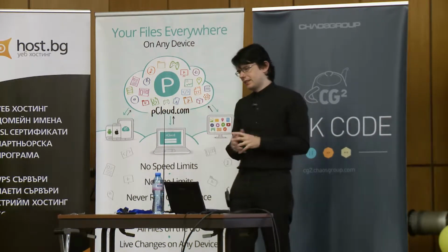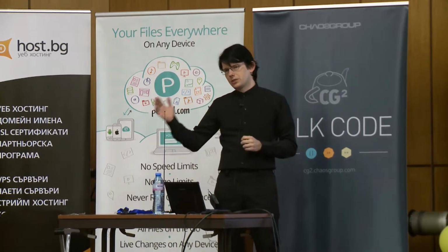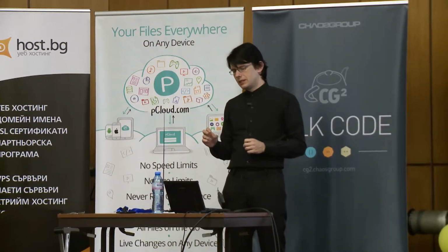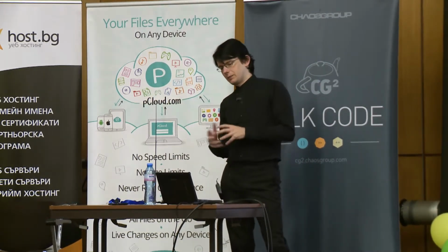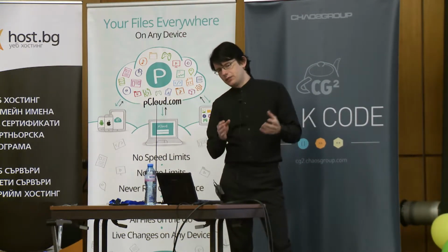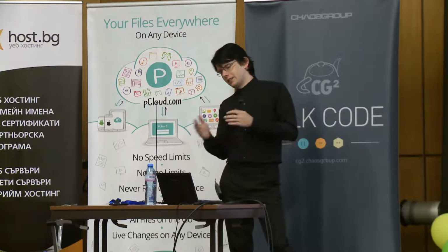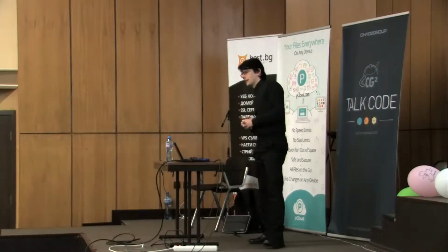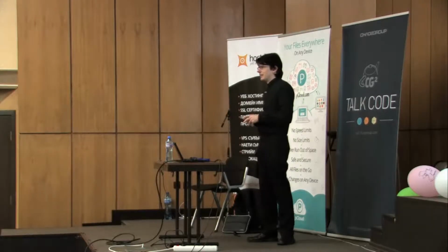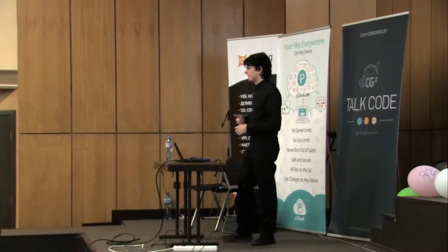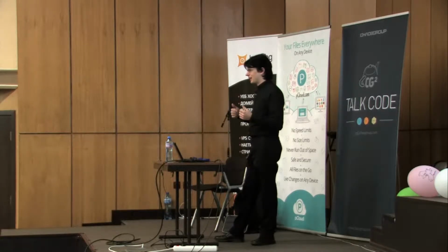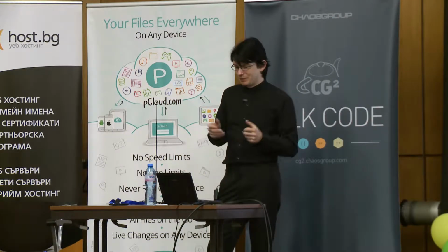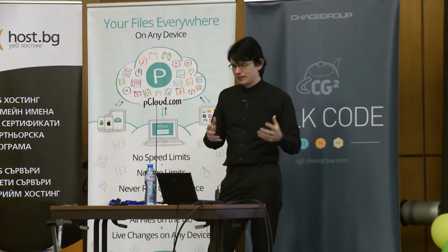The other idea is to convert not to a 0IF, but to a very low intermediate frequency, and then sample that intermediate frequency and work with the samples on that. Whereas in the 0IF, you convert to baseband, and then you sample the baseband data with an analog digital converter. And the ADC can never be fast enough, and it can never have enough resolution. So you want to have as much resolution and as many bits as you can get, and as high a sample rate as you can get.